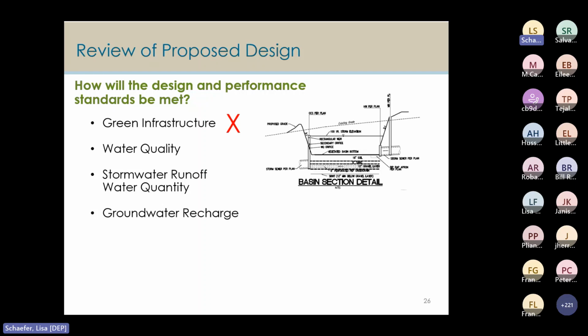And the details for each of the BMPs show most of the requirements for online bioretention systems with under drains, meaning there's weirs and orifices to attenuate discharge from the larger design storms. So far, so good. However, I didn't see the bioretention media specification, so that would be something I would add to my review letter. I also didn't see a maintenance plan, so without these two items, the BMPs don't merit their TSS removal rating, meaning they don't meet the water quality standard. So that would also have to go into the review letter, and I'm going to call that strike two.